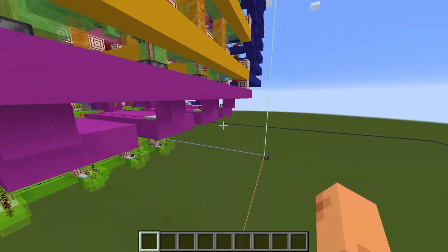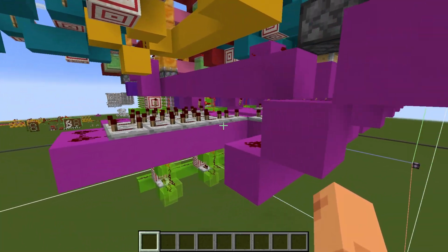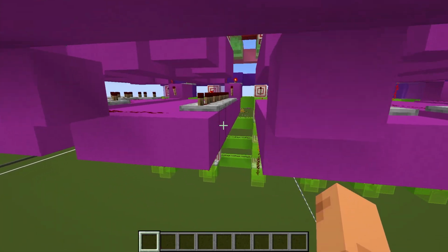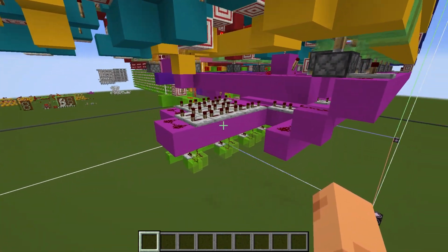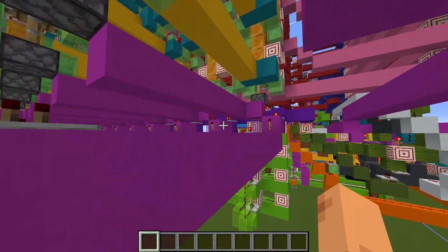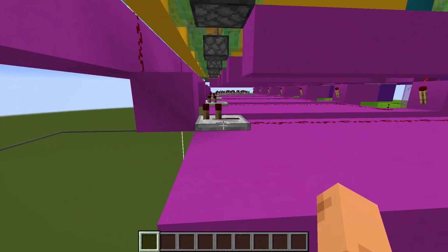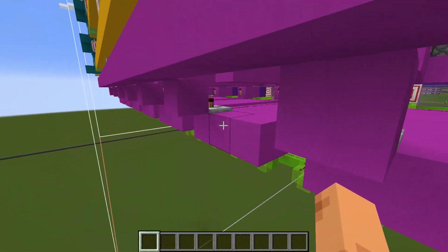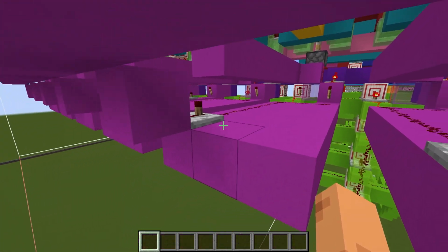Now, this is a very, very slow CPU, by the way. But we have a dynamic clock, or a variable clock cycle, which is timed by these circuits down here. This basically controls the delay for the cycle, given how much delay we need for this computation. So the simple logic functions here only have a delay of like 1 tick. This is a repeater that controls how many ticks of delay you add in. So these are 1 tick logic functions, pretty fast. Here's a 3 tick logic function that has been set to 3 ticks.